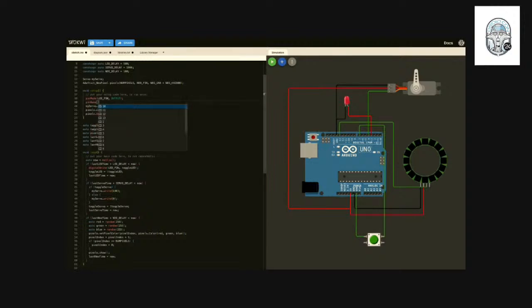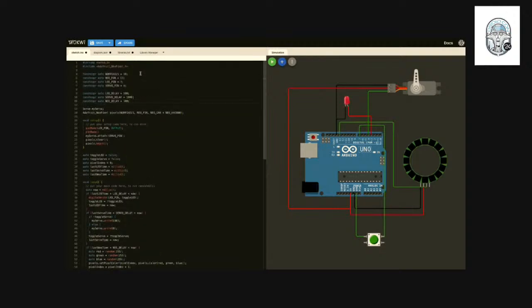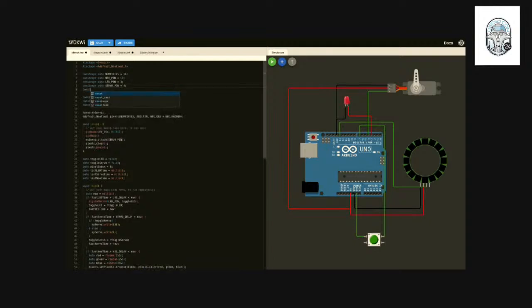Typically, with the pin that you're pulling to ground, you want to make sure it gets pulled up. So we'll add, I can explain that in a second, we'll add the pin number here. So button pin is, what was it, 7. So we say button pin is input pull up.